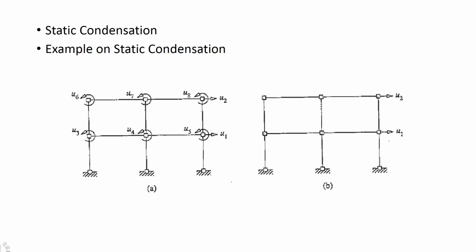Thereby, as discussed in earlier topics, we come to know that the mass of the structure is always idealized at the floor level. Here the mass can be idealized at nodes as point lumps, and the mass matrix now contains 0 diagonal elements for rotational degrees of freedom, but certain known values of mass for translational degrees of freedom.